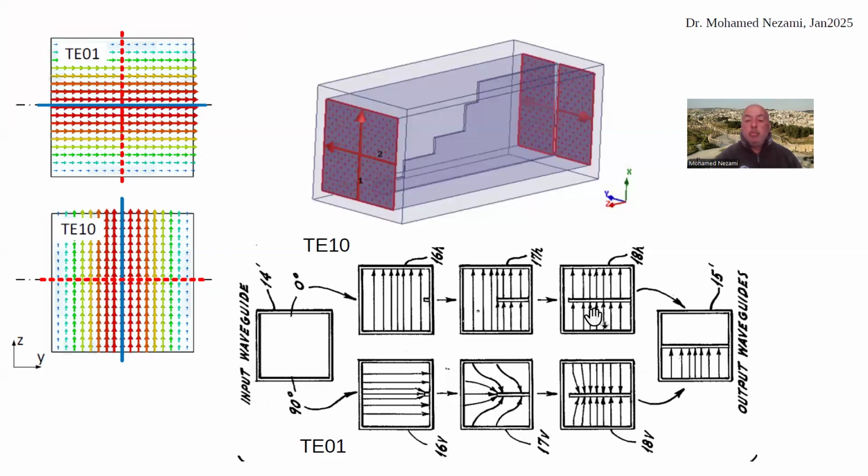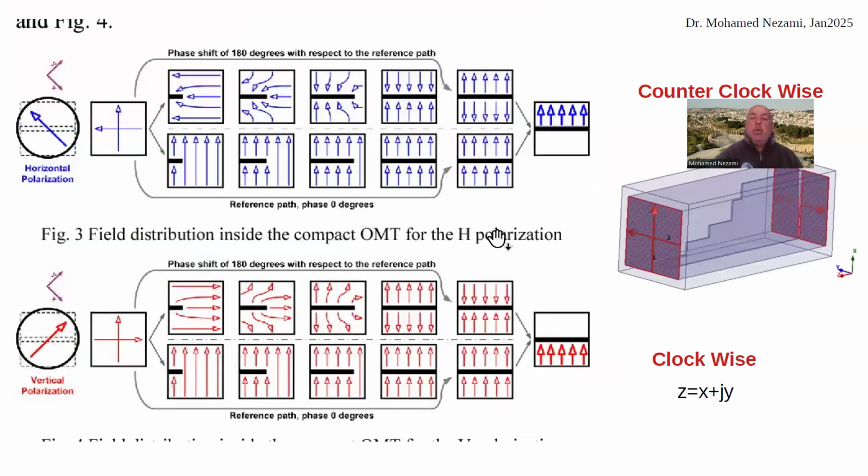You see that the E field is split here into two parts. On the other side, where it's parallel, you can see that as soon as the E field hits that piece of metal in the staircase in here, it starts going into separate modes that are opposite in phase. This happens in both waveguides, and as a result, the E field will cancel, or be minimum, on one, while it's maximum, doubled, on the other one.